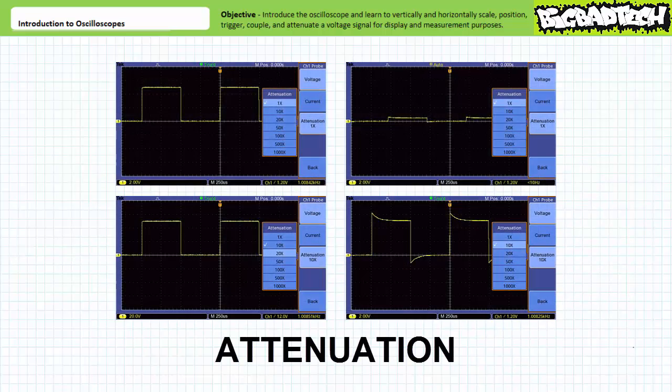In regards to attenuation, if you're seeing values 1/10 of what you expect, you are inadvertently attenuating the waveform. Check the slider and make sure it's in the position you want. Additionally, it should be noted that modern oscilloscopes allow a means of dealing with attenuated input by rescaling it to the original value. If you're using 1x attenuation and the oscilloscope is set up to rescale 10x attenuated input, the results will be 10 times what you expect. Long story short, both the probes and the oscilloscope need to be in the same attenuation mode.